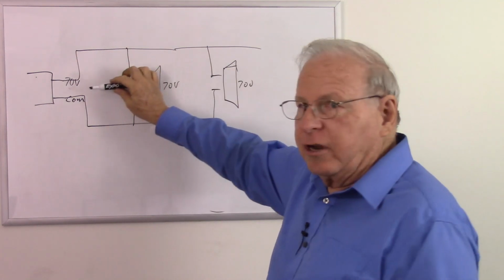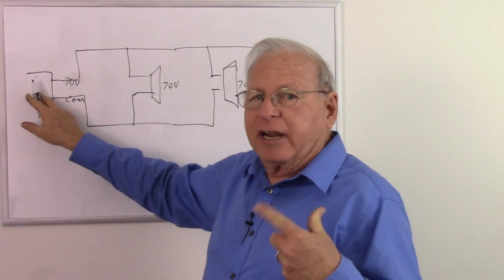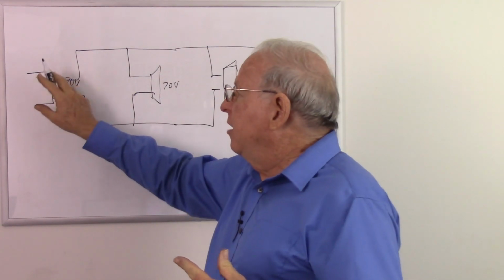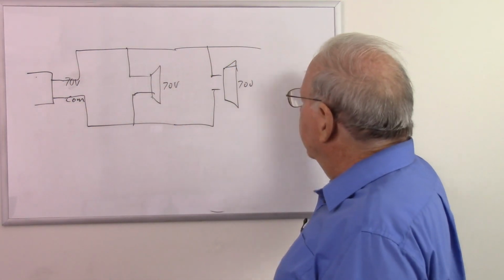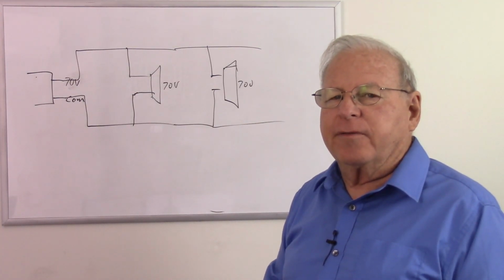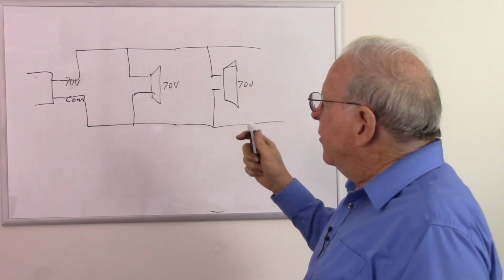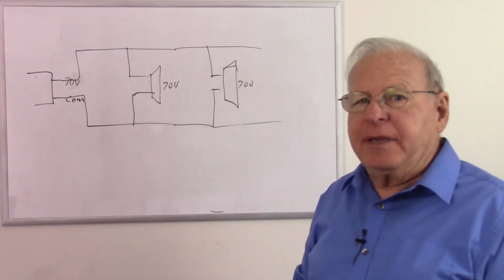Of course, the impedance is going to be half of what it was before, so the amplifier will change its impedance. It'll actually lower its impedance to make sure that we keep that constant voltage at the highest output. And I can do that ad infinitum to have all the speakers in parallel that I want for the PA system. So that is dealing with speaker impedance and with speaker voltage in PA systems.